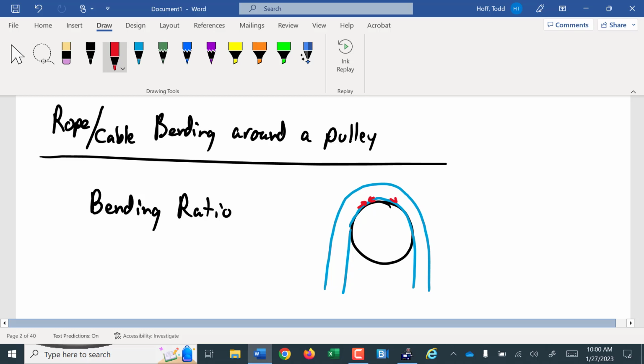They're being pushed together. And the fibers on the outside are being stretched. They're being pulled apart because that rope isn't straight anymore. Think about it. If you bend a piece of plastic, often the side on the outside of the bend cracks because that surface is being stretched. And if it can't stretch that far, it breaks.